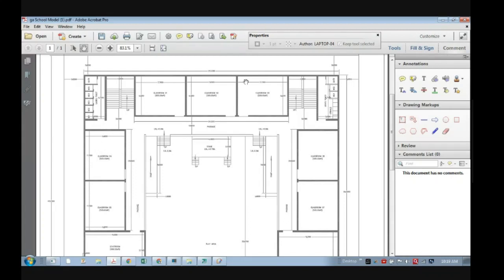So every building may have special requirements. As I told you last time, if it is a marriage hall, then we need column free space, or if it is a stadium structure, we want column free space. So banquet halls, marriage halls, or stadiums will require column free space. There should be minimum columns within the vision. So that is one requirement.